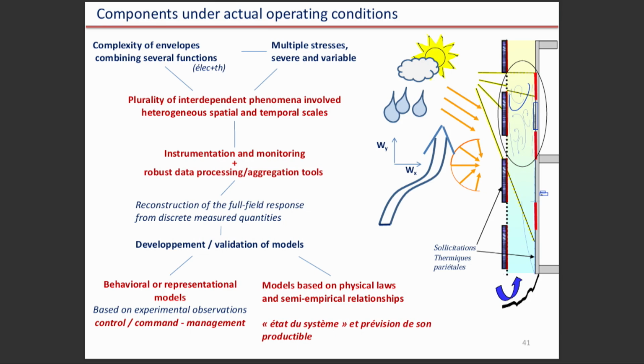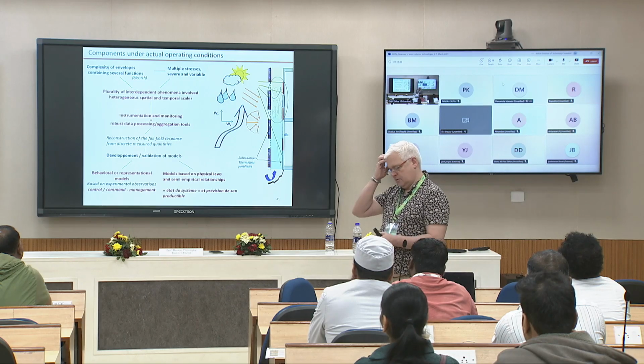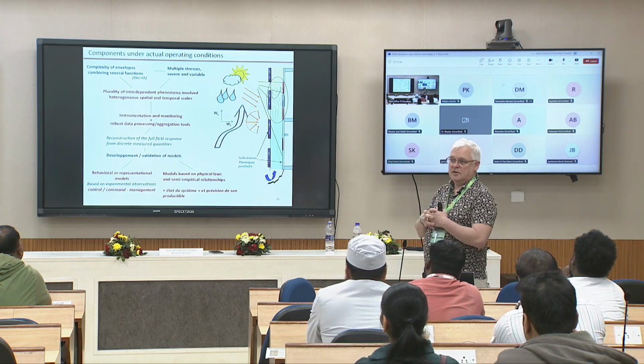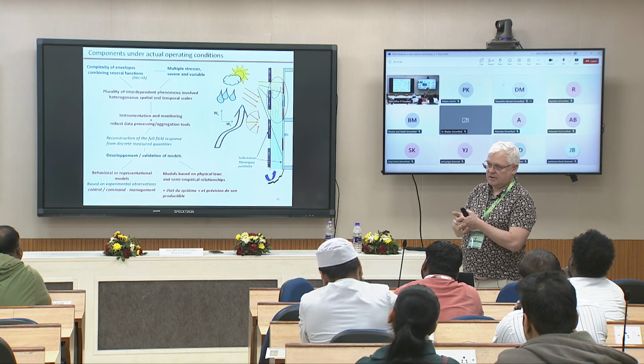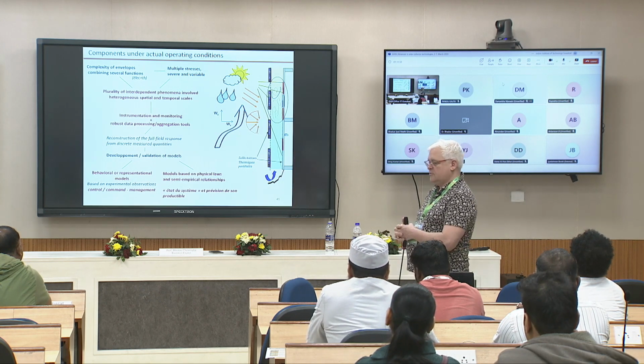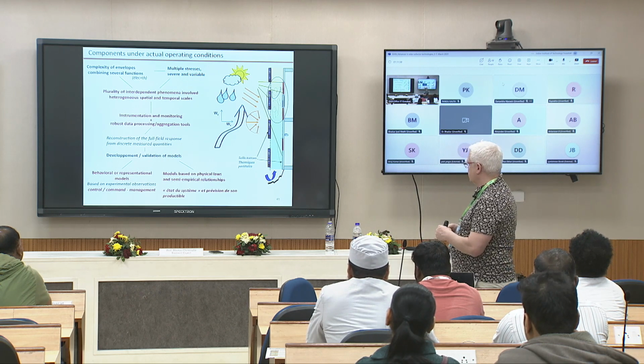One of the key elements of such a facade is to recover part of the heat during winter. There are many configurations with PV materials, and for sure it will be mechanically ventilated if you want to increase the efficiency. Like this you control the air velocity.